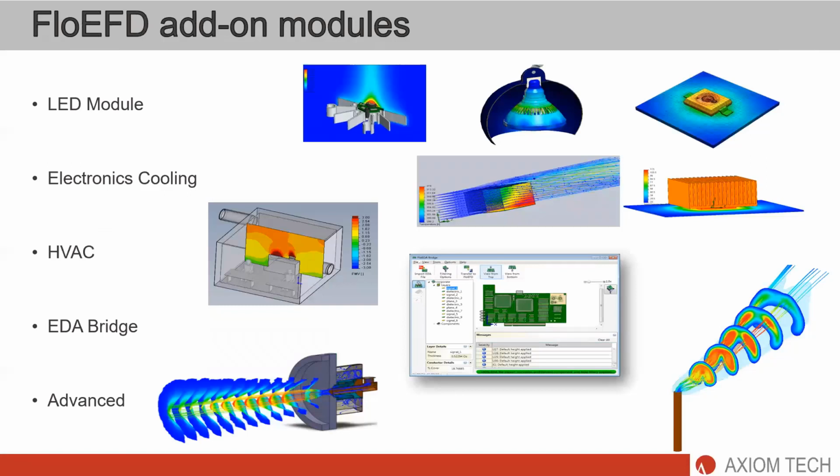And now I will introduce FloEFD add-on modules. FloEFD comes with 5 add-on modules for specific application or special physics. The first one is LED module. It's specific for lighting with LEDs and any type of bulbs and condensation and icing modeling, include also water absorption in solid.